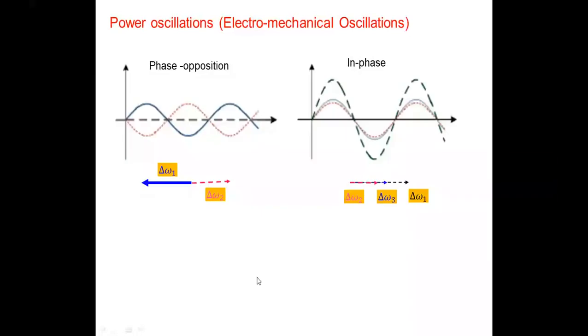Now with this slide, as illustrated, I think we have also discussed earlier how we are likely to have the oscillations, and you can see here a graphical representation. When we talk about the phasor position, it means the variation of rotor angle for one generator and for another generator are exactly 180-degree phase shifted.